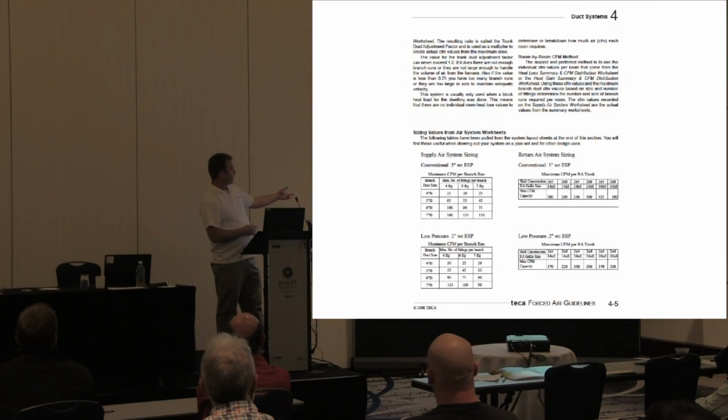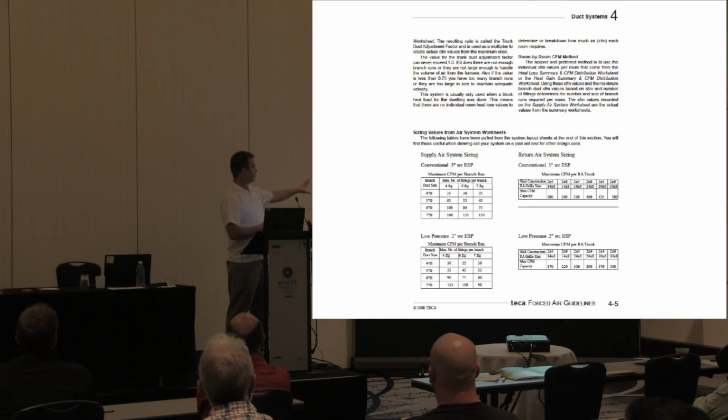The other thing on this list that I wanted to go over is if you're putting in just a gas furnace and an air conditioner, you would use a different chart with a different set of volumes. We would use what they call the 0.3 chart, where the static pressure in the duct is a little higher, so we can run it a little faster to get where we have to go, because the furnaces don't require the flow through them, and we have more range of flow.